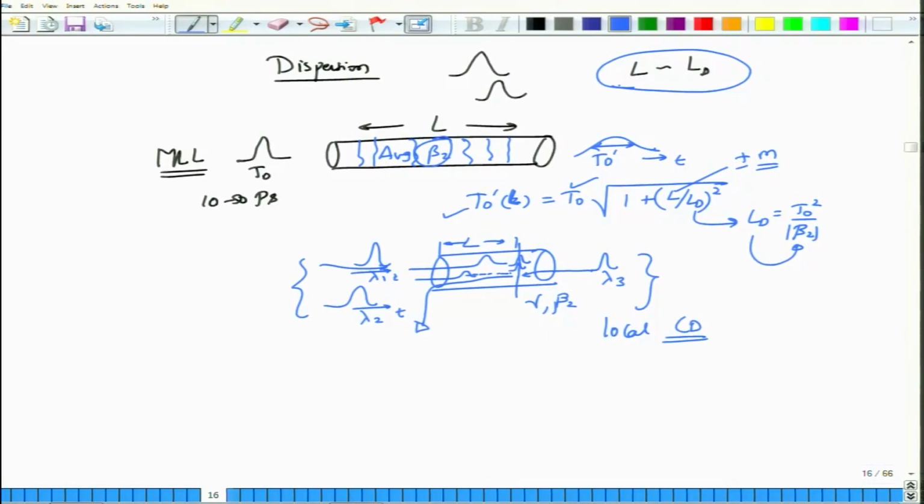There is a way to overcome that problem, and that would involve looping the fiber. You send the pulse in there, and then you can put an amplifier just so that you are covering up the losses in this particular span, and as the pulse, which is about a few picosecond long, you start looking at the pulse at the output. So, you have a scope here. First time the pulse will go in, a portion of the pulse will go into the loop, a portion of the pulse will come out. So, you are going to look at the pulse here.